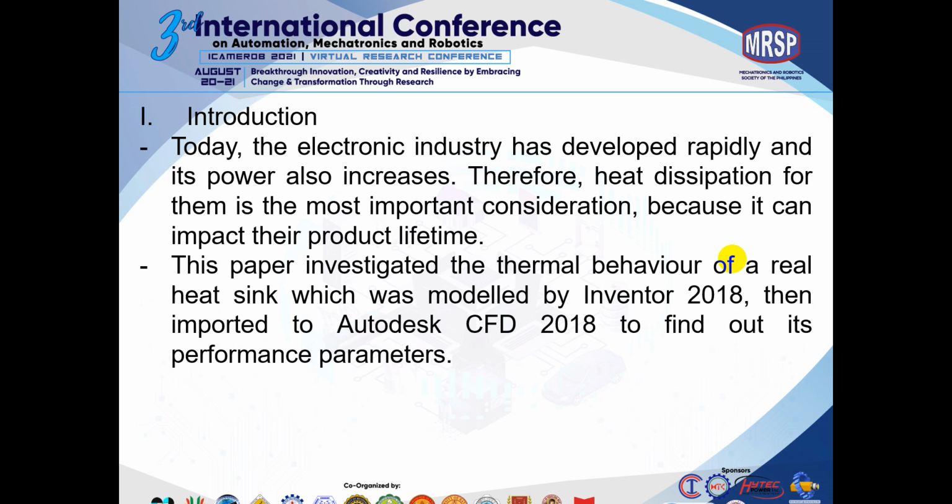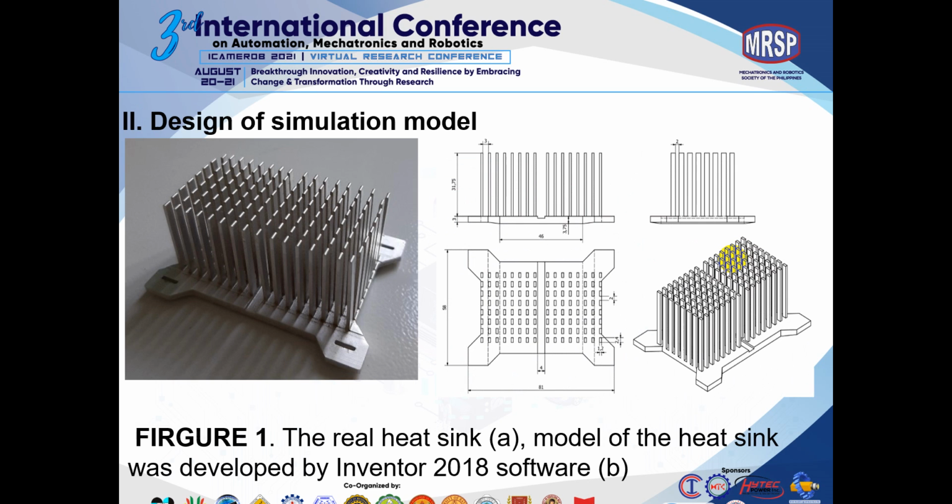In this result, we investigate the thermal behavior of a real heatsink, which was modeled in Inventor 2018, and we imported it to Autodesk CFD 2018 to investigate its thermal performance. You can see on the left is the picture of the real heatsink.